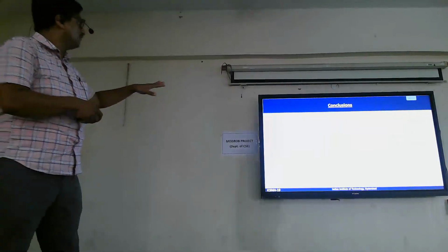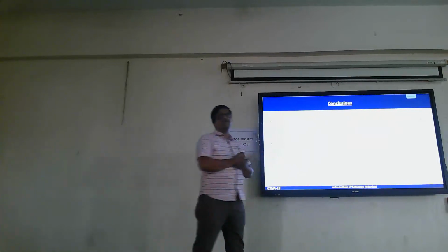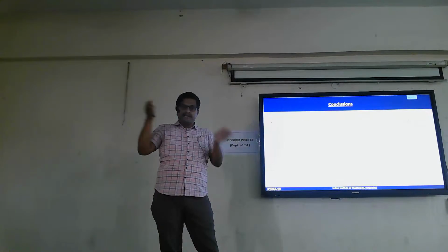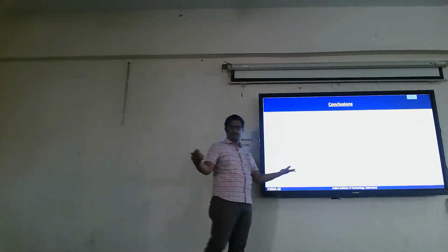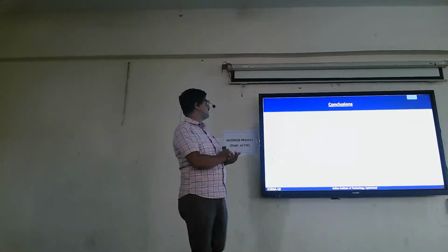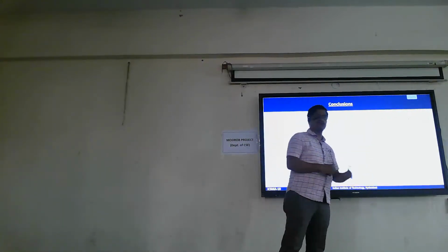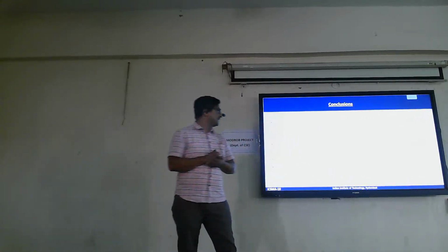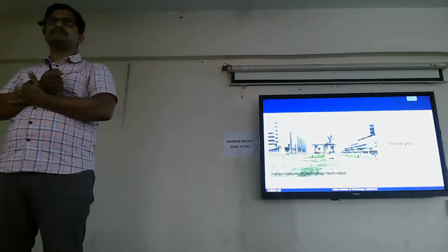So with this, I want to conclude that dynamic strain aging characteristic serrations are observed in the intermediate temperature regime. The serrations were not seen below 400 and above 600 degrees. In this temperature regime, solute interaction with dislocations might be the possible mechanism. The failure mode changes from transgranular to intergranular at high temperature. The creep rate is 2 orders lower in the present alloy compared to the cobalt alloy which I showed you before, and the dislocation glide controlled mechanism will be the dominant creep mechanism, as already mentioned. Thank you.